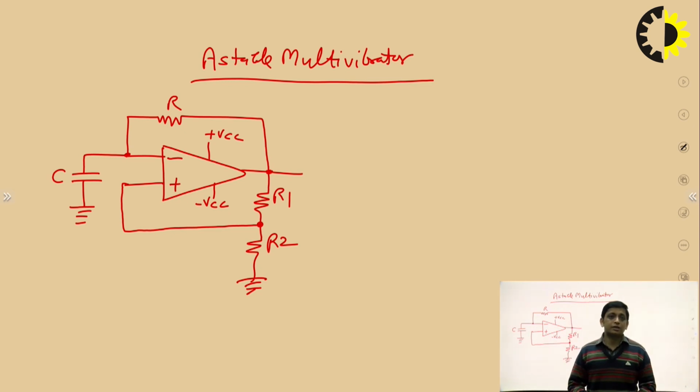So you people have studied that circuit, that application. That application is voltage comparator. In open loop configuration, op-amp has very limited applications. The reason is that in the open loop configuration of op-amp, the output gets saturated. Means at the output, there will be only two values, plus Vsat or minus Vsat. So there are very limited applications in open loop configuration, and one of them is the voltage comparator circuit. But op-amp will get saturated also in case of positive feedback. Fine.